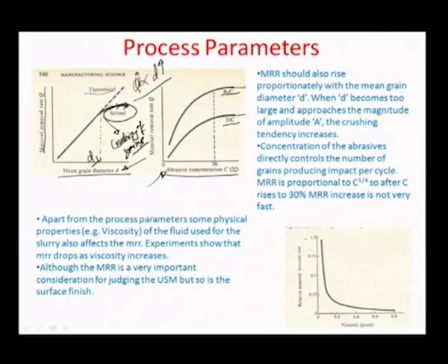Okay. And that is because between the tool and the workpiece, supposing this is the tool surface, and this other is the workpiece surface, there are a lot of grains on it. So you can only pack the available area of the tool to its fullest capacity. For example, if you load more grains, the density of the grains per unit area of the tool-workpiece surface would keep on increasing up to only a certain limited value, beyond which any further grains cannot be